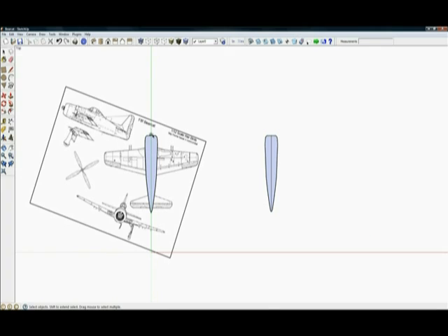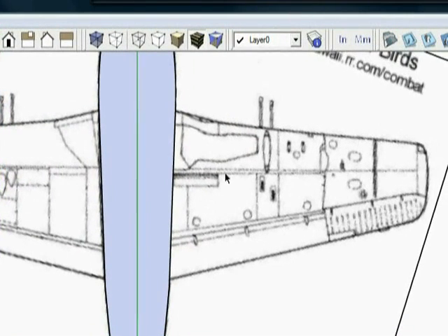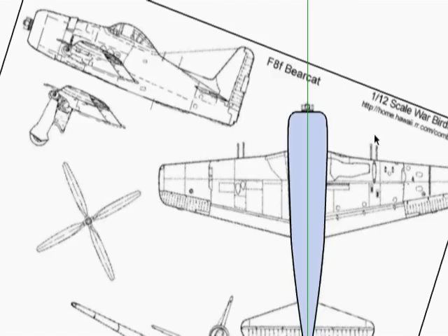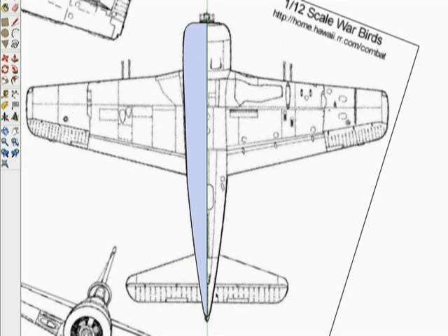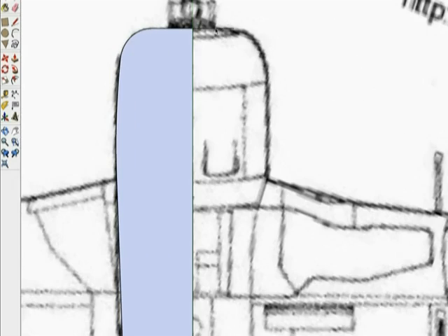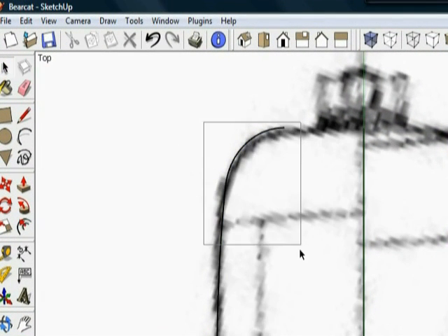Now I'm going to delete everything except my center line, because I'm going to use that same center line that's referencing the side pieces for a wing. We're going to do basically the same thing and draw out one and then flip it along and so forth. And you'll get an idea how this works. There are a lot of different ways of doing that. I can just do a little marquee select, delete, just taking all these little line segments, do it again here.